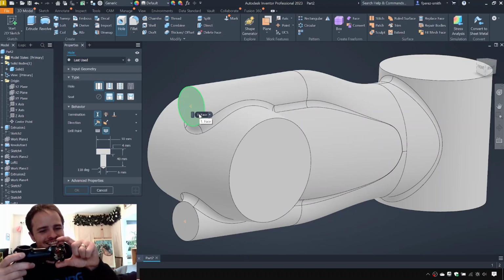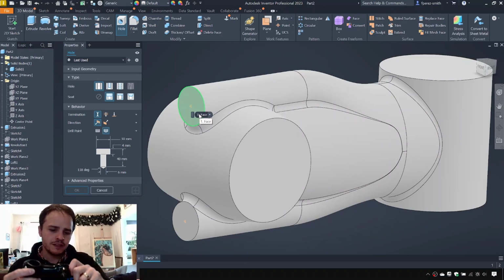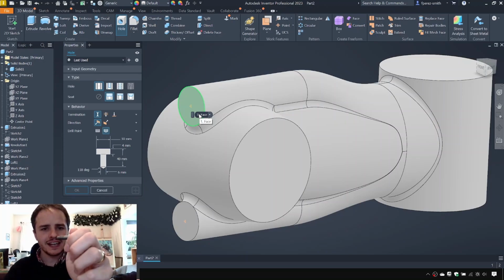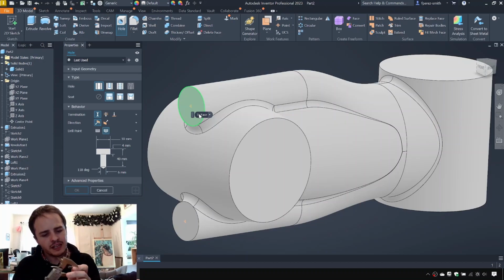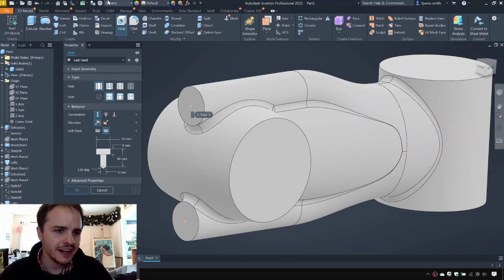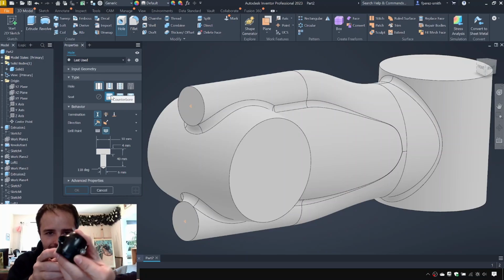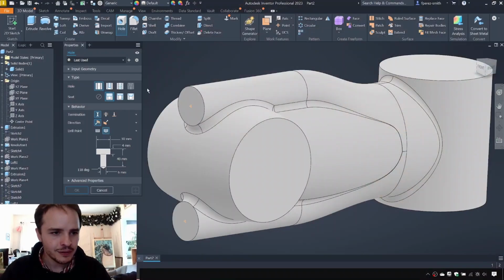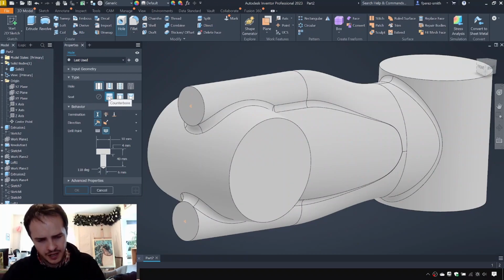And we are going to make these holes. So if we take out this bolt, here we go, we can see that we've got a bolt of yay big. We can use our calipers to measure it. And we can see that it's an 8mm bolt. Very good. So we'll come along here and we are going to make a simple hole with a counterbore. I should have pointed this out as well. I'm not sure if you can see it inside the model, but there is a little seat in there for the head of this bolt, so it sits a little bit more flush, called a counterbore, and we're going to include that.